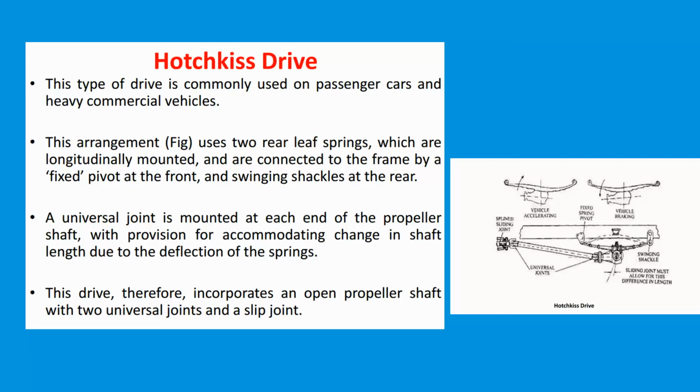The torque tube type, when combined with rear coil springs, requires an additional locating element such as a Panhard rod. This is not needed with a torque tube and leaf spring combination. Some Hotchkiss drive shafts are made in two pieces with another universal joint in the center for greater flexibility, typically in trucks and specialty vehicles built on truck frames.